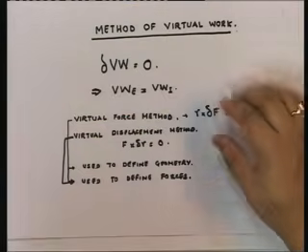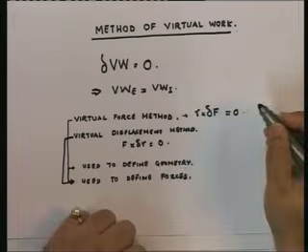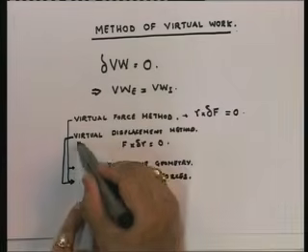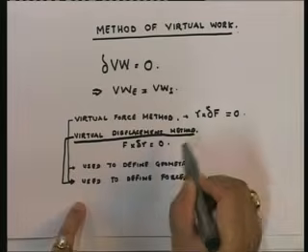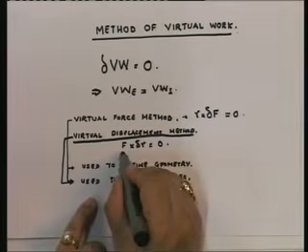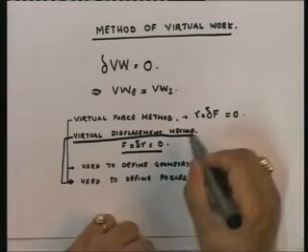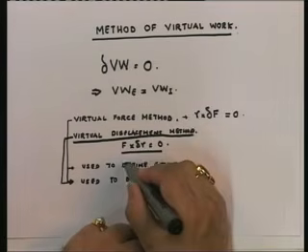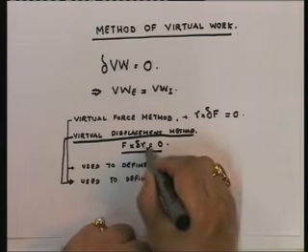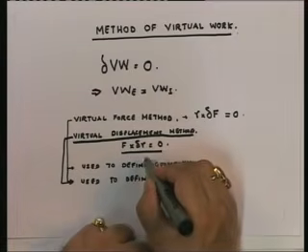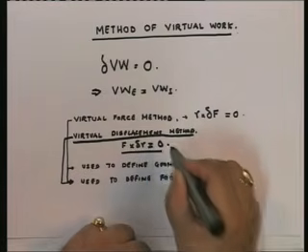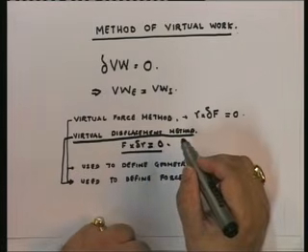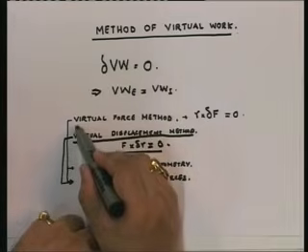If you look at it, there is the virtual displacement method, which is the common one that we always refer to, that you have a system of forces and you subject it to a set of virtual displacements, and then the total work done is equal to 0. However, you have another method.